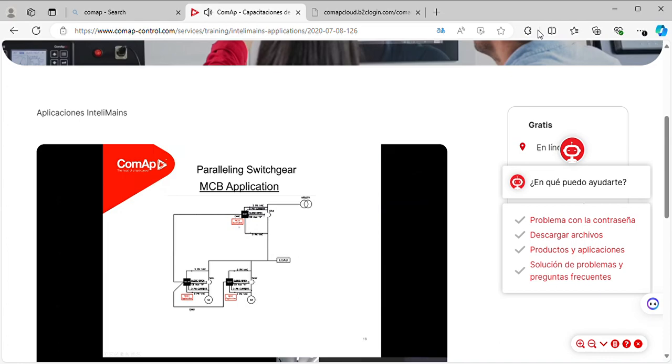As you can see here, it can close and open this breaker, plus it takes a feedback. It has a three-phase bus voltage measurement, three-phase grid voltage measurement, plus current measurement. Your genset controllers are independently taking care of individual genset control and protection, but they talk to each other over the CAN bus. Upon grid failure, the controller would send a signal over the CAN bus to start the genset, synchronize if required, and start feeding the load. And once the grid returns, we can reverse synchronize and do a soft load transfer.